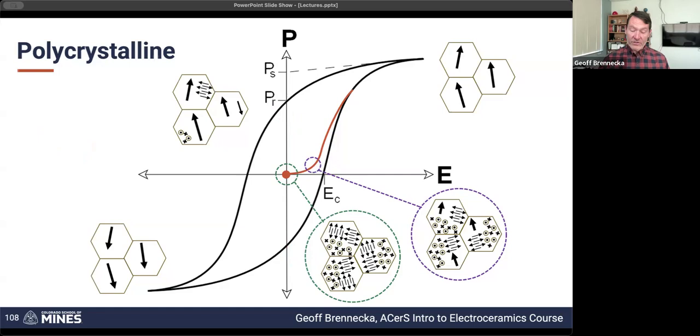So if we do, for some reason, want to end up back at this completely random state, the best way to do that is just go through the phase transition again. So if we heat the material up into its centrosymmetric prototype structure, so in this example, we'll take that barium titanate, heat it up to 150 C or 200 C or 500 C. We get high enough above the Curie point that it's definitely cubic and it's relaxed, and then cool it back down again. We will see this completely random behavior again. Again, there's modifications to that with defects, and we'll get into those a bit as we go. But as a starting point, this is what a ferroelectric hysteresis response looks like.